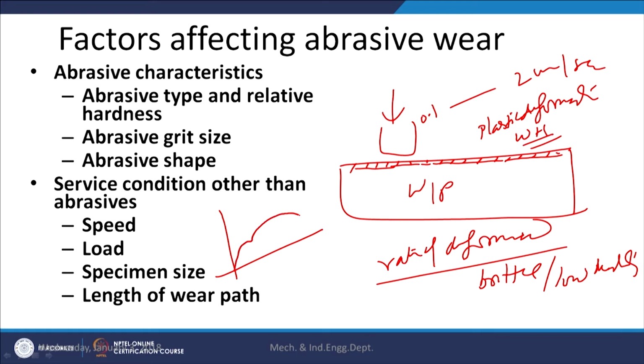This is what we can see from one simple diagram also. During the tensile test, if we perform the test at a low strain rate, then we may find one plot like this, say at 0.1, which is basically the cross head speed of 0.1 mm per minute. And if we do it at 1 mm per minute, then we may find higher yield strength and higher ultimate strength, and lower ductility in terms of the percentage elongation.